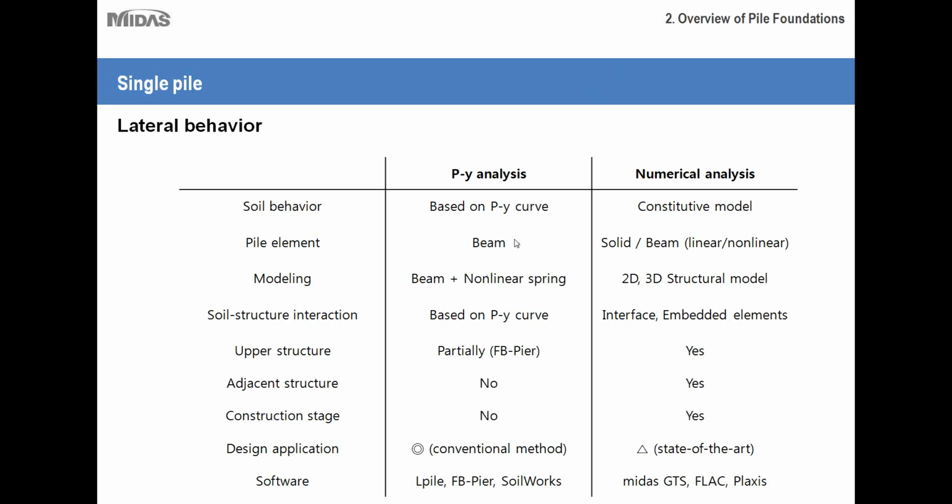As far as pile elements, in PY analysis everything's modeled as a beam, but with numerical analysis you can model it as solid elements or as a beam element. So you can model both linear and nonlinear behavior. Depending on your project scope, you may want to model it as a solid element, but we'll get more into these options in the next couple of slides.